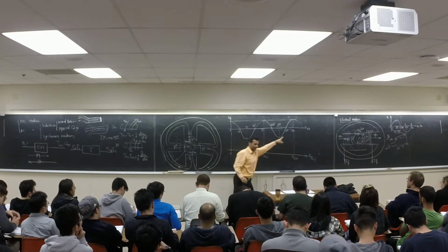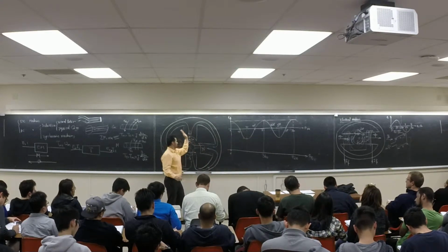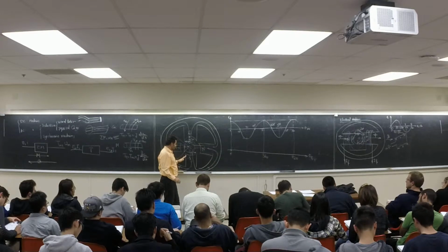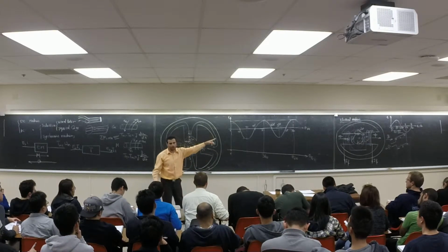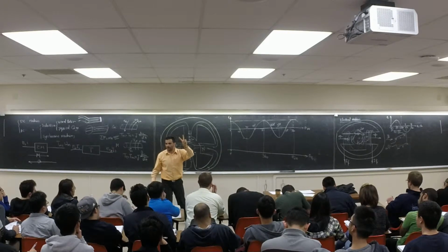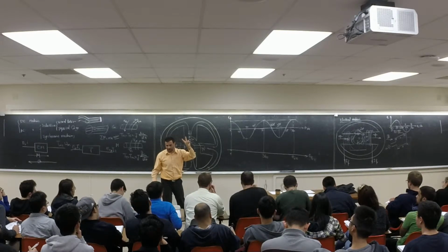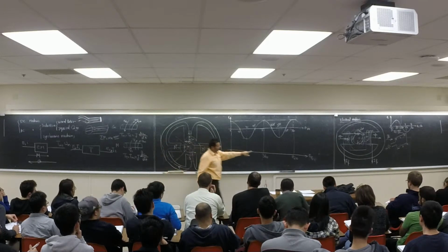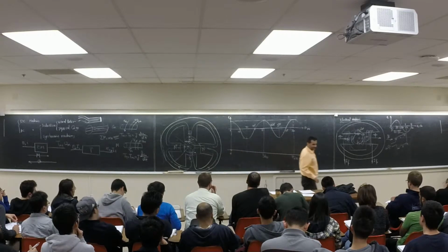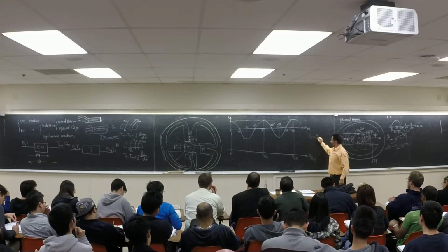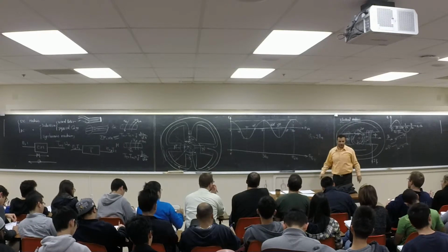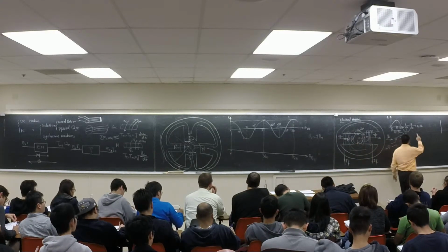It's a mechanical degree, I put it here. I said 0, 45, 90 degree, 135, 180, and went that way, right? Well, look at the waveform. We have 2 cycles. 2 cycles means 2 times 360 degree, right? So what's the relation between theta E and theta M? Theta E is double. 2 theta M.